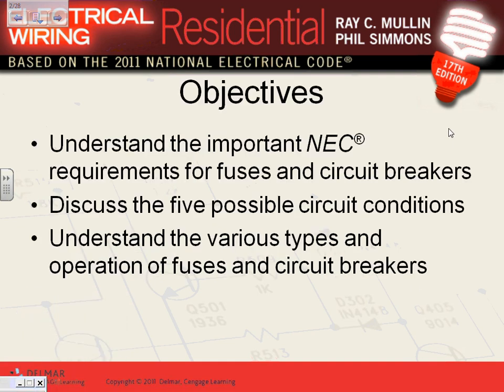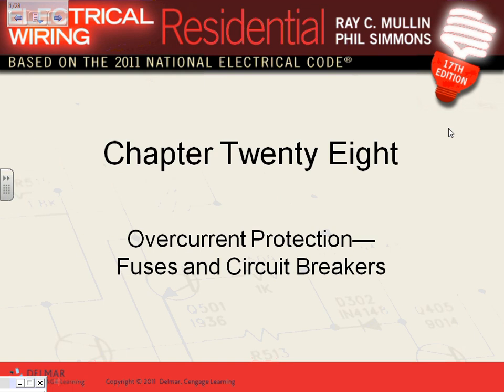Okay, so a couple of things, guys. Overcurrent protection devices, fuses, and circuit breakers. The code requires all equipment and cables to be protected from overcurrent. When you go to different industries, you're going to see that they protect from things other than overcurrent: overvoltage, undervoltage, frequency, over and under. So today, the only thing we're going to talk about, guys, is protecting from overcurrent.